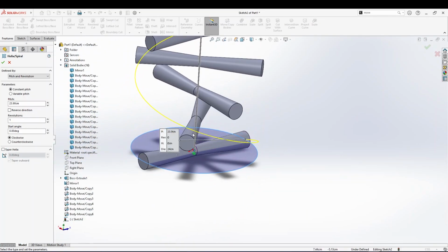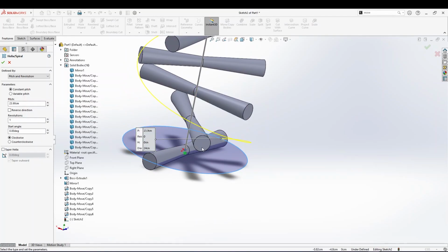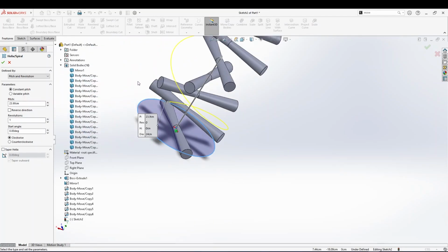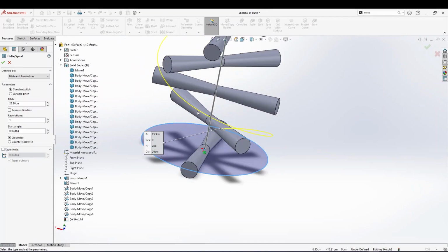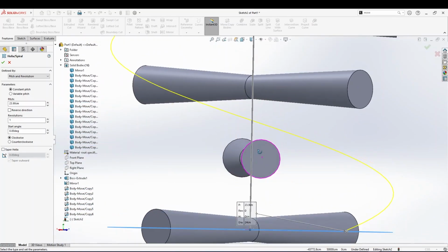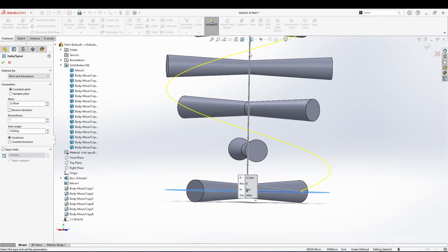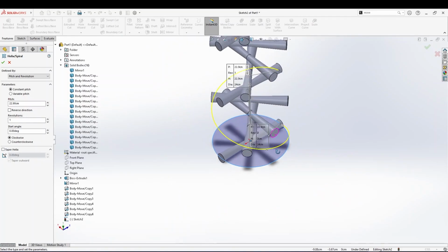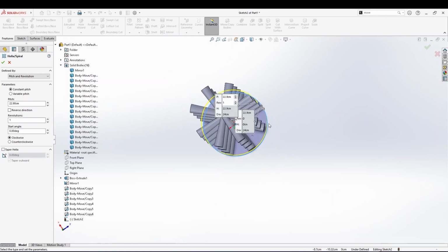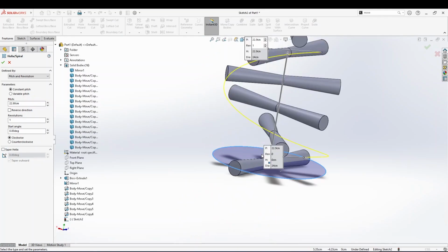And we also want the spiral, as I told, to move along these faces, so it will kind of touch them. Not necessarily touch, but will go close to these faces. And it is defined by the pitch. You can press arrows here and you will see that the spiral just goes up and down. The pitch is actually the height at which the spiral makes a full rotation. If I look from the upper side, the spiral makes the full rotation, and the height when that happens is the pitch.